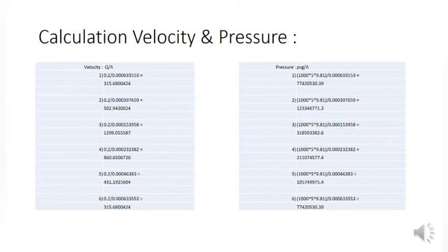The pressure, we use rho V g over A. So the rho is 1000, the V is the volume, which is 5, and the gravity 9.81 over A. We take the calculation from the area before and put it in here, and we get the answer for pressure. This is static pressure.